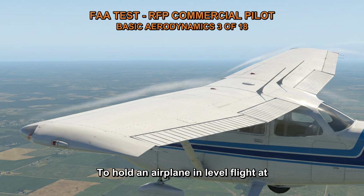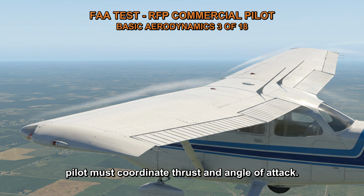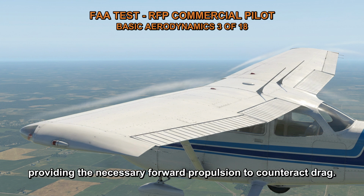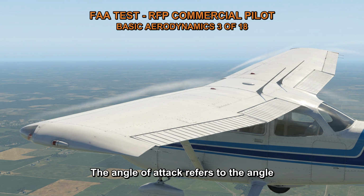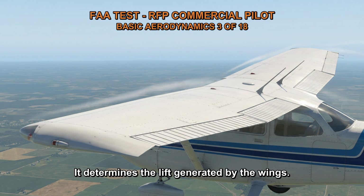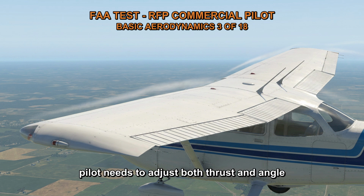To hold an airplane in level flight at airspeeds from very slow to very fast, a pilot must coordinate thrust and angle of attack. Thrust is the force generated by the engines or propulsion system, and it is responsible for providing the necessary forward propulsion to counteract drag. The angle of attack refers to the angle between the chord line of the wing and the oncoming airflow. It determines the lift generated by the wings.